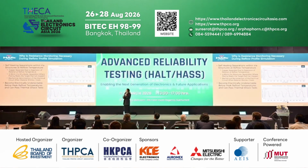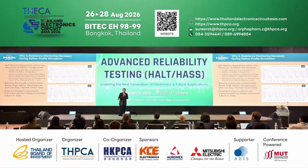However, this kind of failure can be self-healed. As temperature cools, all the copper structures will reconnect. And if you test at room temperature, all the resistance seems to be normal again. That's why if you don't do any resistance monitoring during reflow, you will miss this, because it recovers at room temperature.